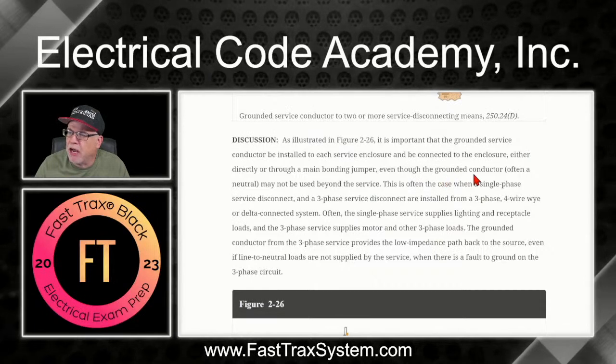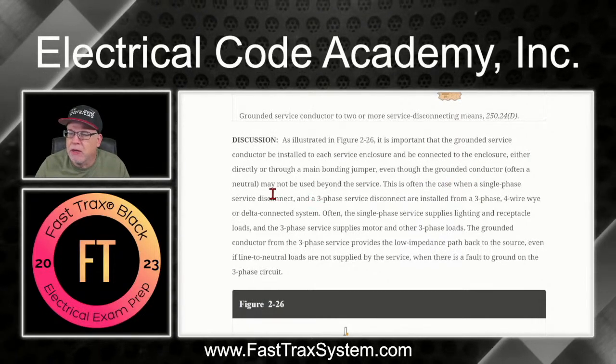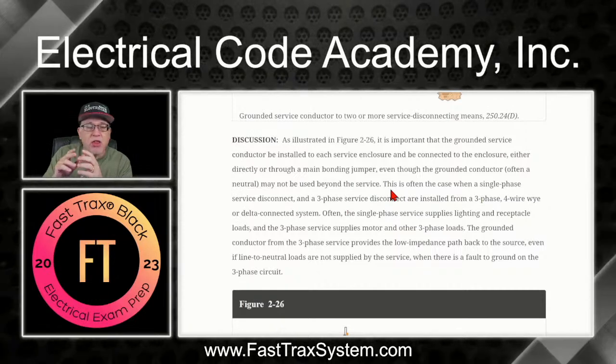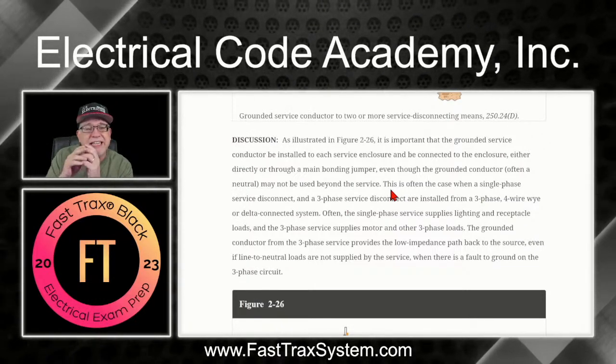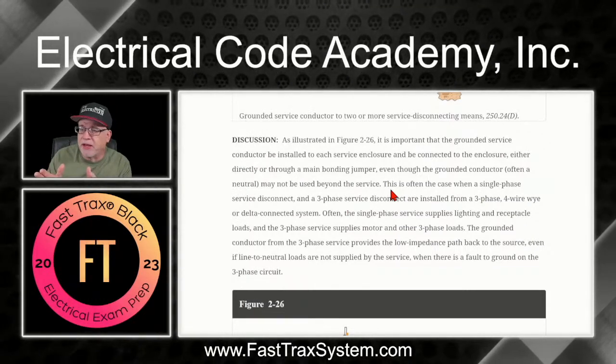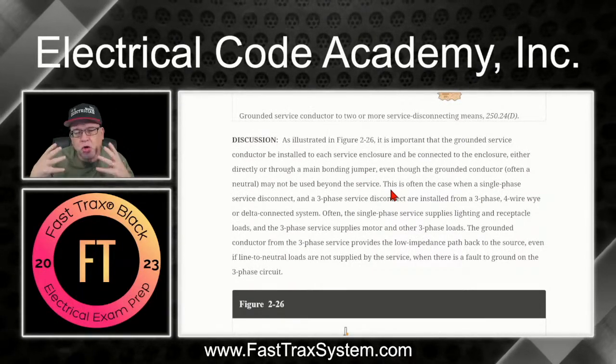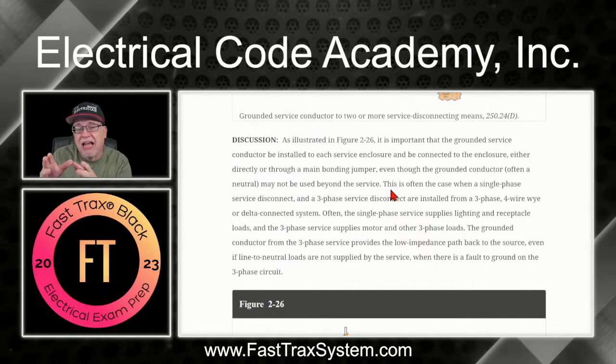Even though the grounded conductor, often the neutral, may not be used beyond the service, meaning you bring it to the service, maybe you don't need it downstream because you have only three-phase motor loads that don't need a neutral. Whereas in the other panel, you need a neutral, okay? So you brought the neutral to the service equipment. Beyond that, you may not need the neutral at that point. So it uses this illustration.